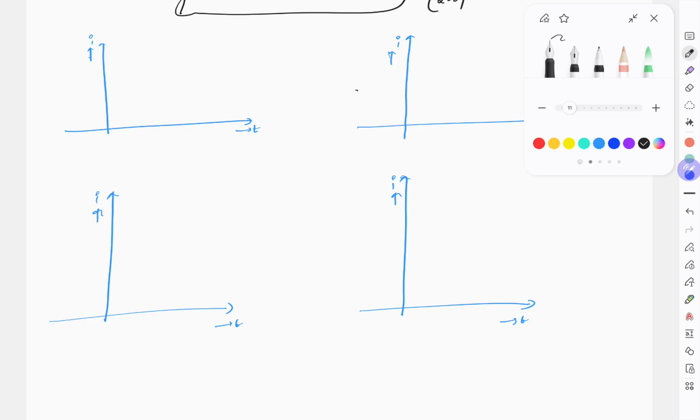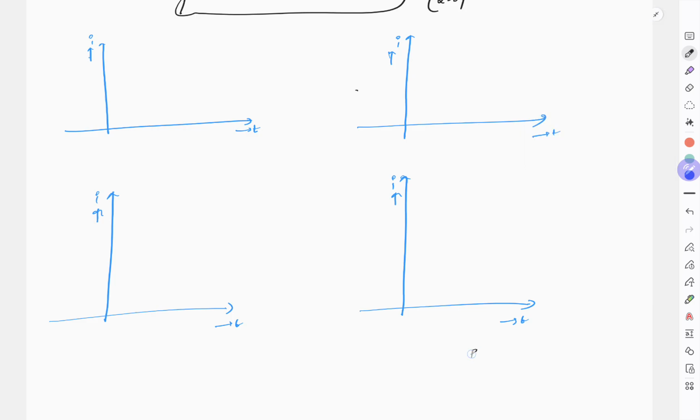But suppose if R equal to 0, the plot is this. R equal to 0 means alpha equal to 0. It means that zeta equal to 0, right? Alpha equal to zeta omega n. So how can it be? It is pure sinusoidal because it's undamped. It is like this, right? Okay, that is fine, you understood.